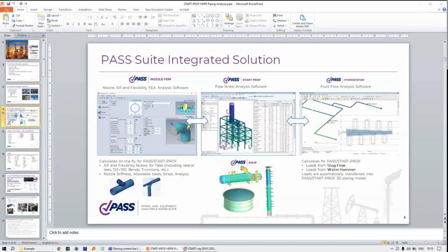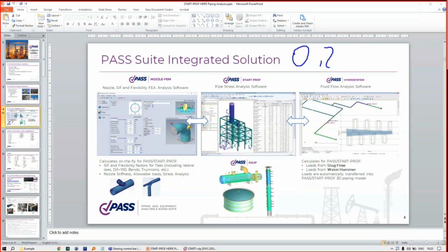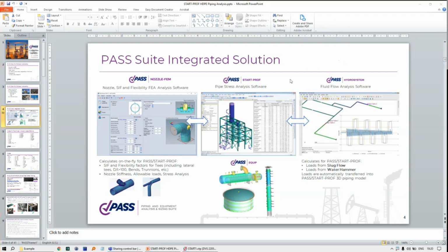Okay. So the next, the temperature range factor, how do we define it? The vendor can provide it, but in some codes you can find its value as 0.85. Sometimes it is used as 0.85, sometimes 1.0. It depends on the manufacturer's requirement. And actually it depends on the thermal properties of the material and the wall thickness.